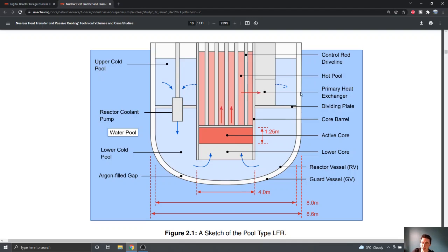And then as it moves around the reactor, the outer edge of the reactor is being cooled by the swimming pool, and that's going to cool down the fluid. And so as it cools, it's then going to want to move back down to the bottom of the reactor because of its now negative buoyancy. And so we can see just by looking at the reactor that even with a loss of power, there may be some mechanism for the coolant to circulate by itself. It won't be, of course, as strong as if it was driven by a pump. And we want to see, how is it circulating, and does it circulate well, or are there any issues we might need to worry about?